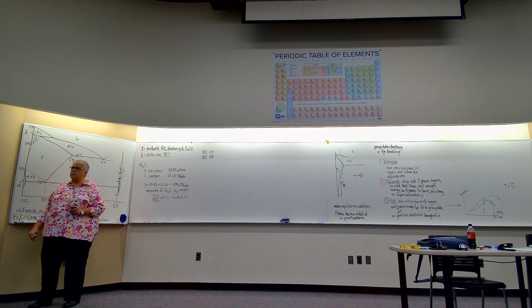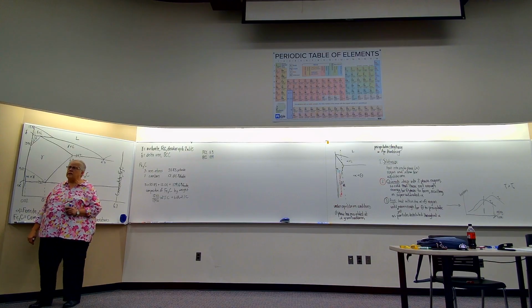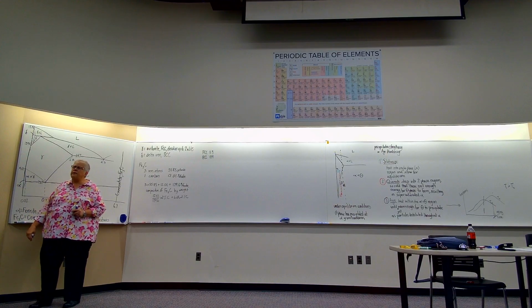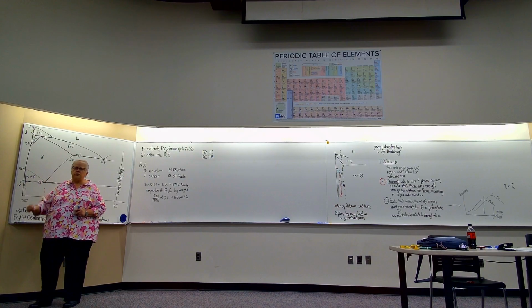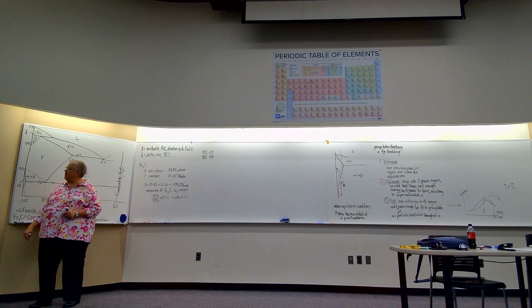You probably can still on YouTube maybe see a video of a piece of wire across 2 sides of a furnace. And it's kind of limp, BCC, get high enough at one temperature, it shrinks to FCC. And then it expands again when it gets to delta.